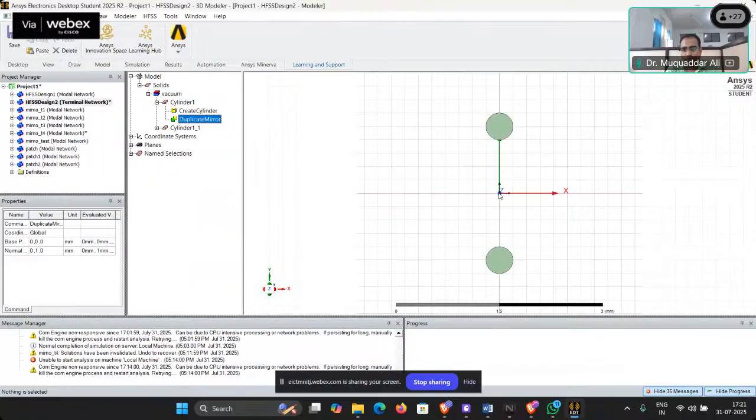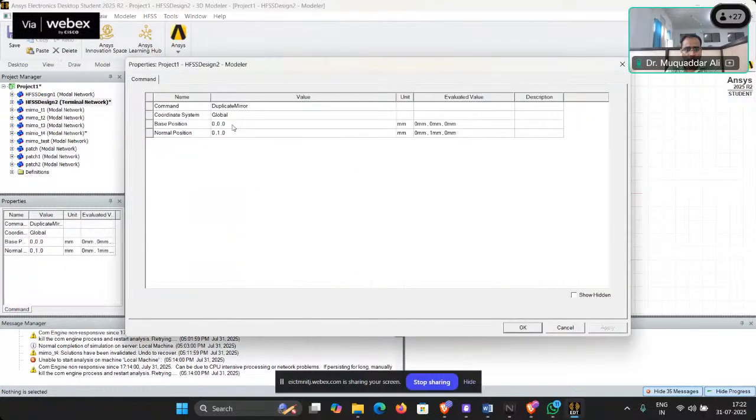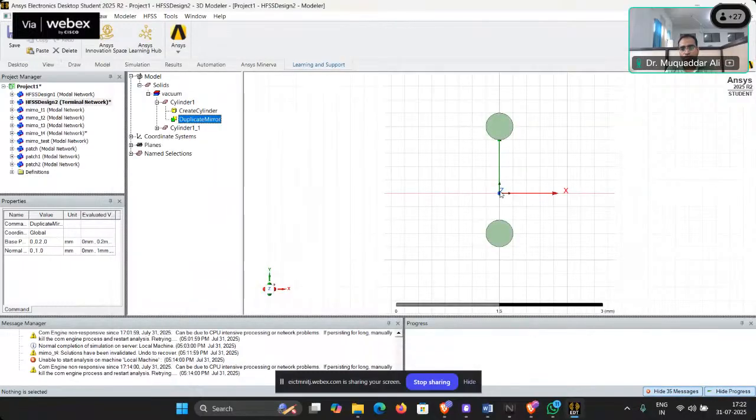Now, again reset this. I'm creating a copy in y direction. Okay. So now from the origin point, you can see we have 1, 2, 3, 4, 5 blocks away from this point. This is our original object. Its copy is also 5 blocks away from this position. Now, if I set this to 0.2, the base position in y-axis I have changed by 0.2. Okay. So earlier the mirror was placed in the xz plane at y equal to 0. Now the mirror is placed in the xz plane, but at y equal to 0.2.